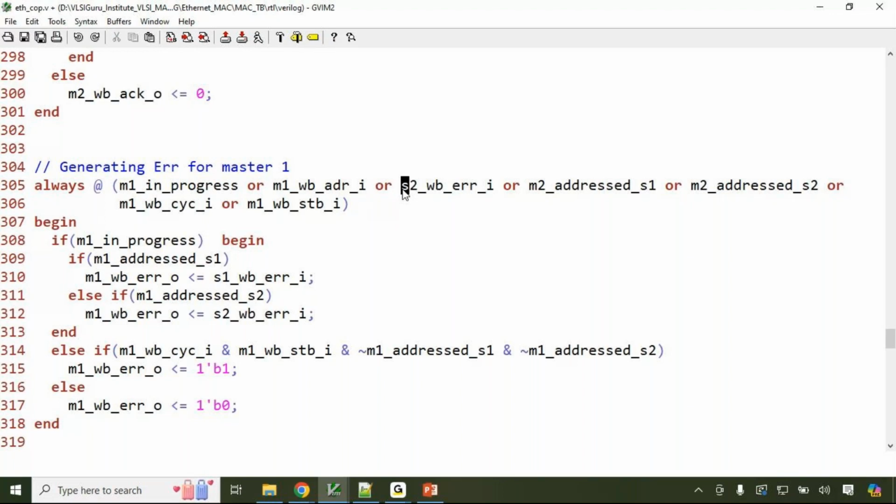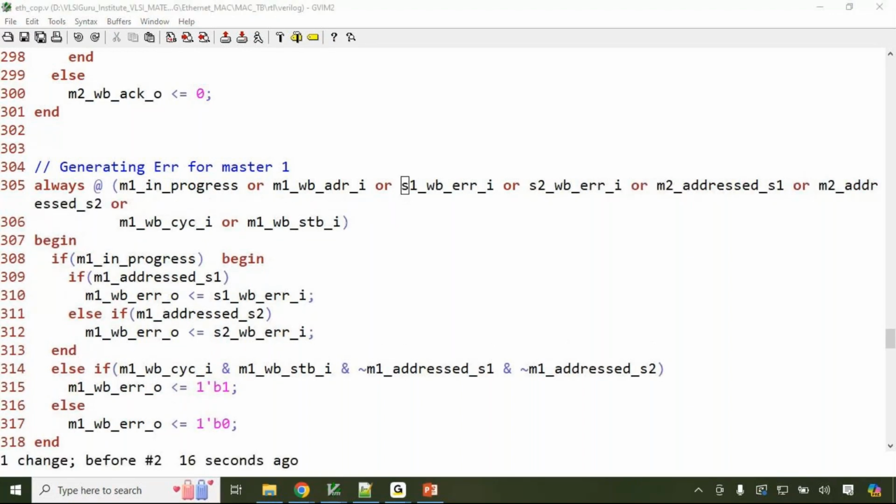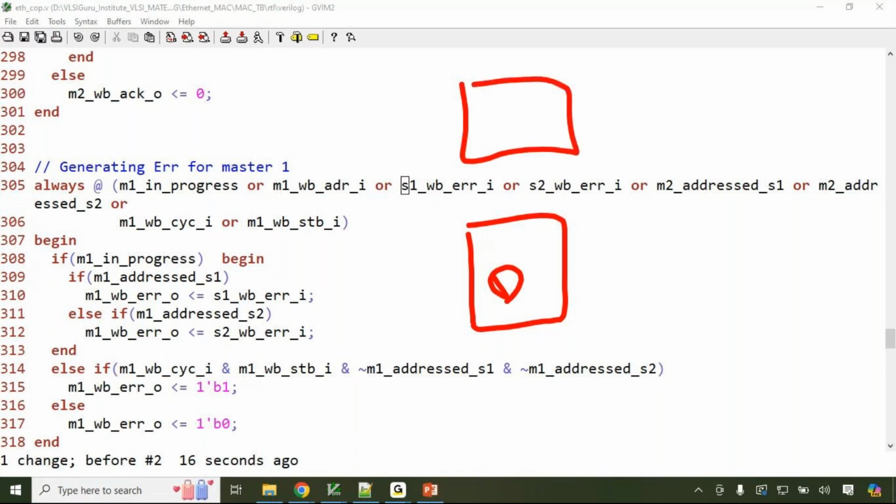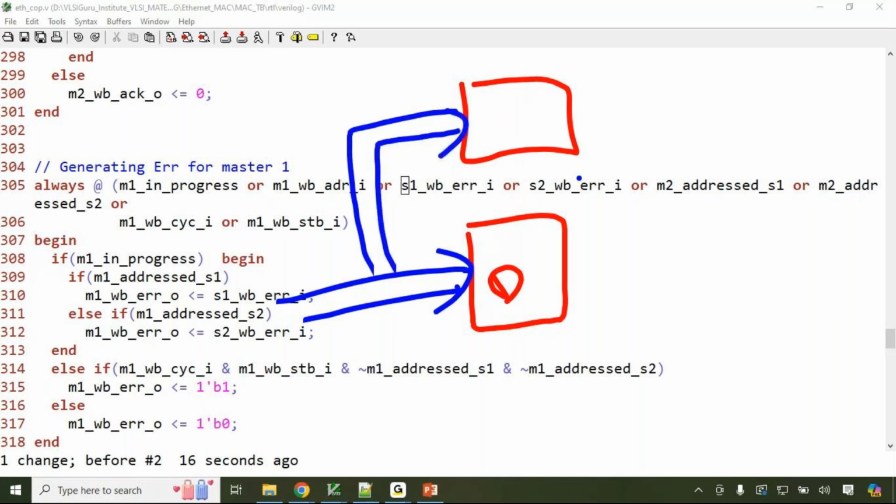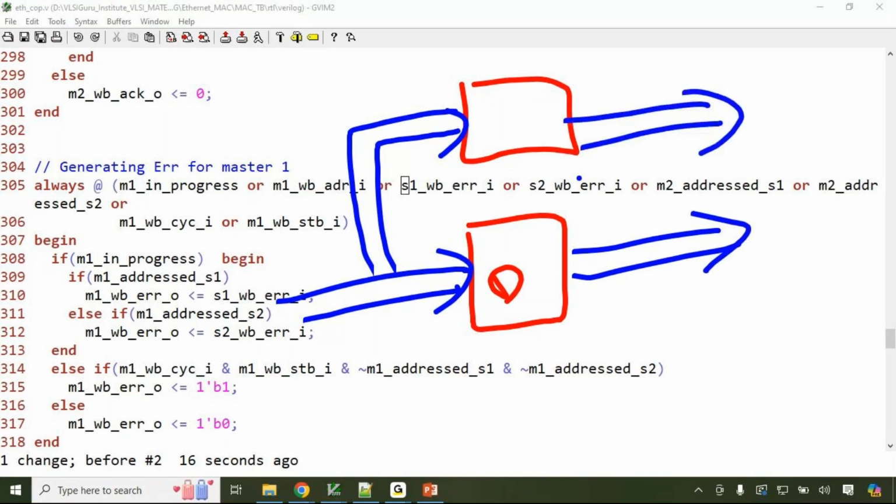So for that, what my verification engineer does is, he has a design. This design is provided by whom? The design team. He develops his own model called a reference model. Then he applies some inputs, the same inputs to both design and reference model. Based on the outputs that come from both, he compares them. If both match for every scenario, then it's fine. The design is working fine. If it doesn't match, he scans the design.